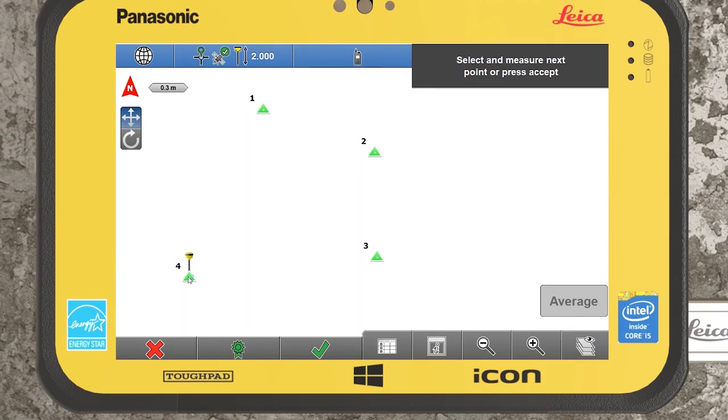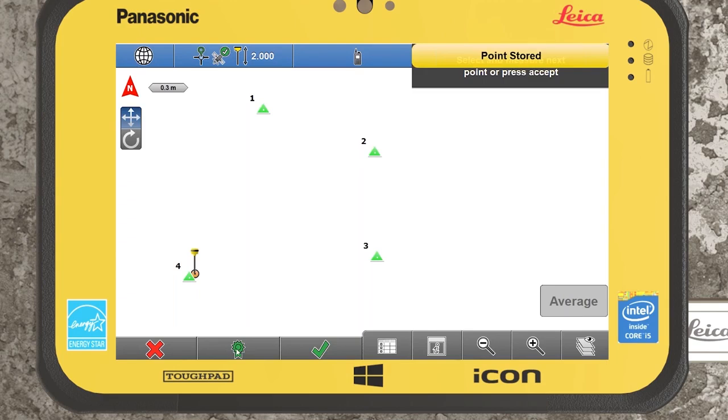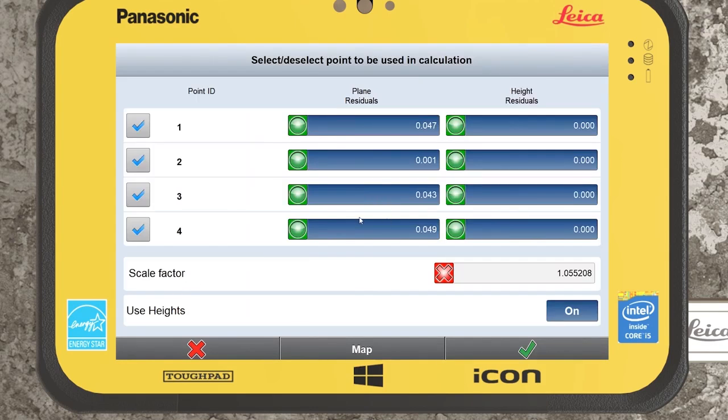You might get one that has an outlier. So if I select to remeasure this point and select average, you might have one point that's been damaged or not. Okay, and what we'll see now is that when we record and purposely add it off, the errors will increase. If I deselect number 4, they all drop back to 0. But if I include it, it throws in an average. So although I was 150 mil out, it averaged the error, which inflicts error on the other stations. So you can deselect and find out where the error is. I can see it's clearly relating to this station 4.